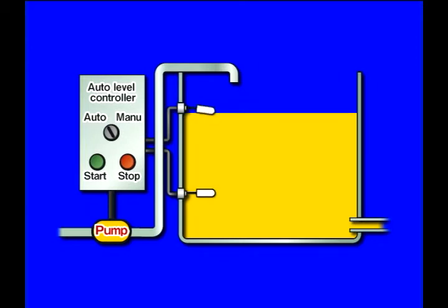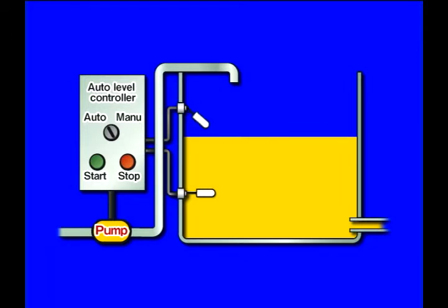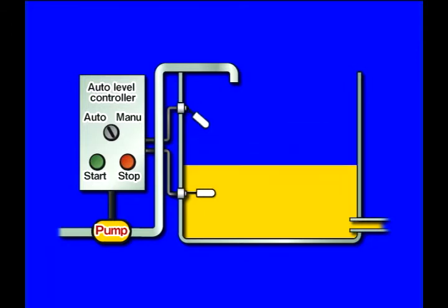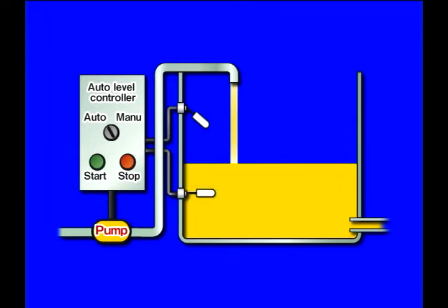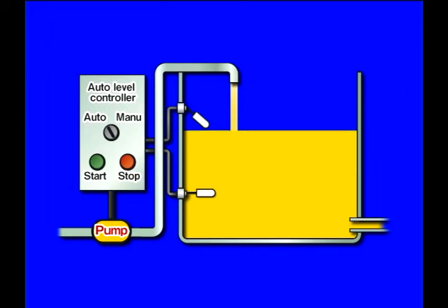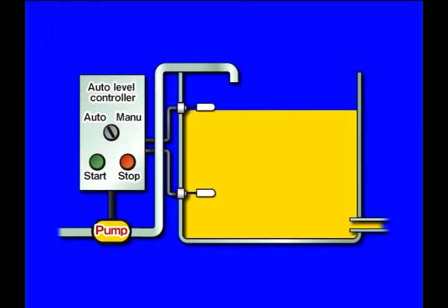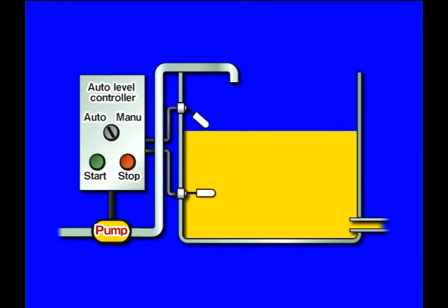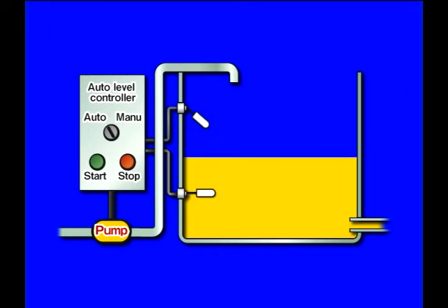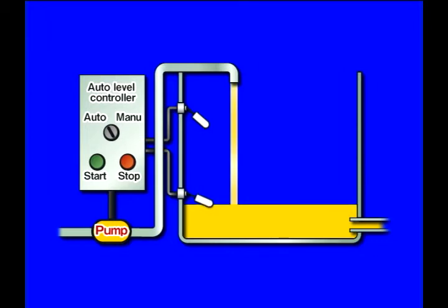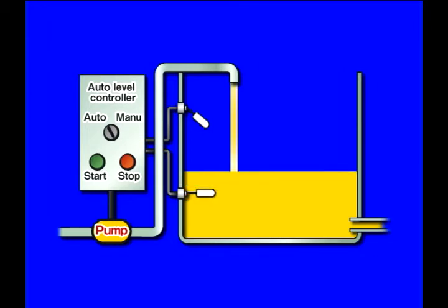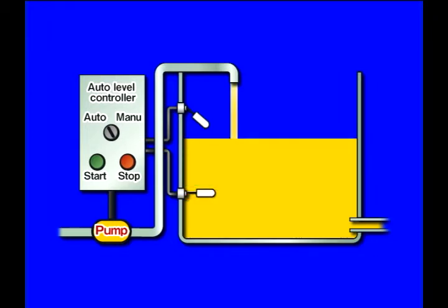The motor that supplies power to the pump generates a modest amount of heat while operating. However, when the motor has been stopped, its temperature gradually begins to decrease. If the motor's temperature becomes cooler than the ambient temperature, condensation on the casing and coil could result. Condensation inside the motor can result in overcurrent, an event that takes place when insulation resistance between the coils decreases, leading to a short circuit.